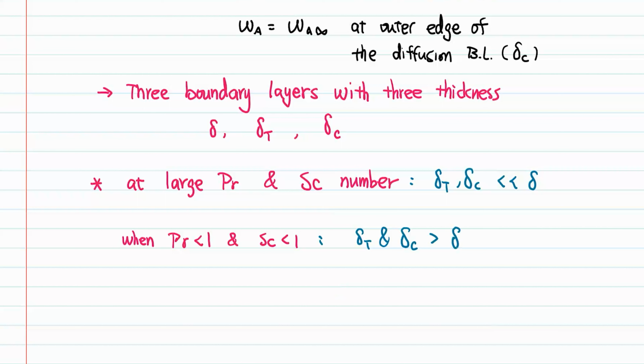And then also something that we want to note here is that if you're looking at mass transfer systems, sometimes the solid surface can be introducing mass to the system or at the interface, right? So let's say if you have a piece of salt that's slowly dissolving in water, then at the solid surface, you might actually have some velocity contributing in the normal direction.